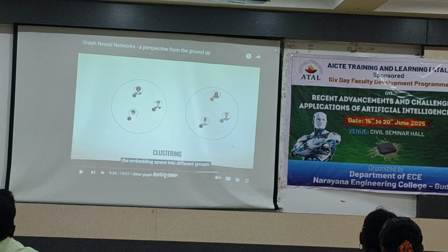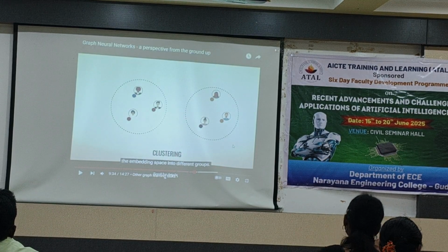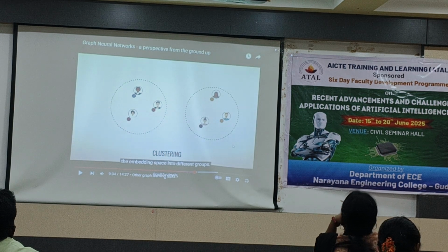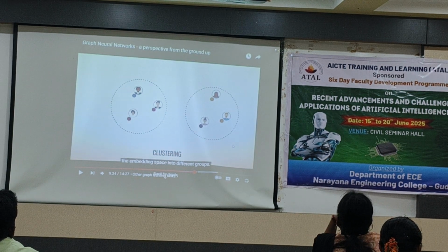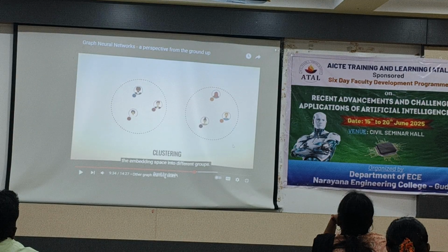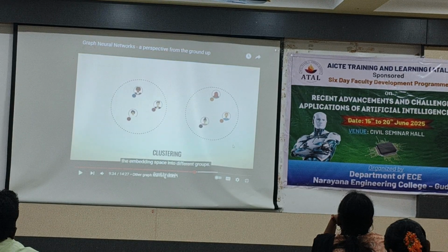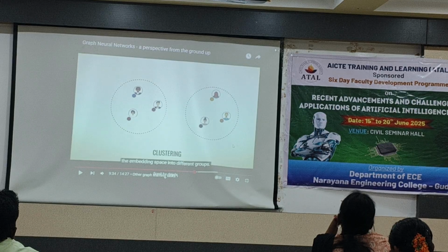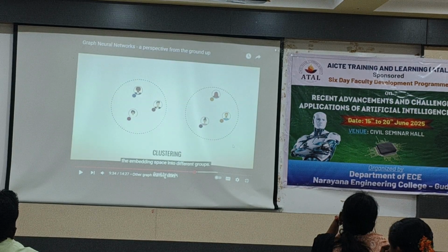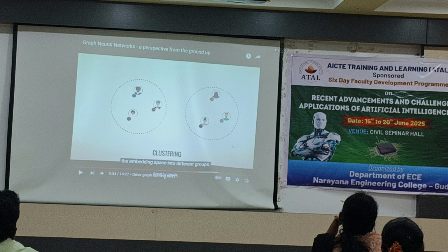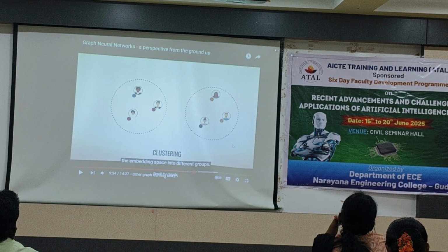This is some clustering. Actually, K-means clustering, if you have heard of it anywhere, at any time. This is one of the algorithms we use. Clustering is like, for example, when it is related to circuit theory, right? For example, one set of logic has more interaction than the other set of logic. So this group of cells should be placed in one corner of the chip, and the other group of cells should be placed in another corner of the chip, because there is no interaction, but these close cells have more interaction, which has a timing dependency, the critical path. So this clustering will help decide where to place those cells in the floor planning stage of the chip design.